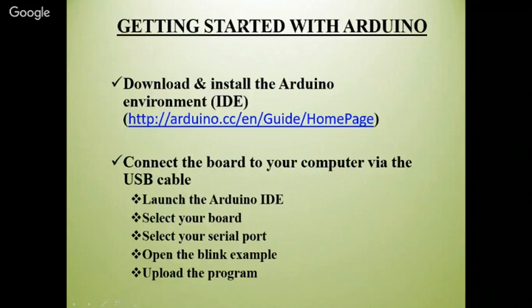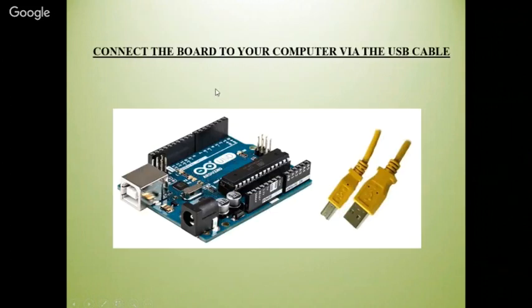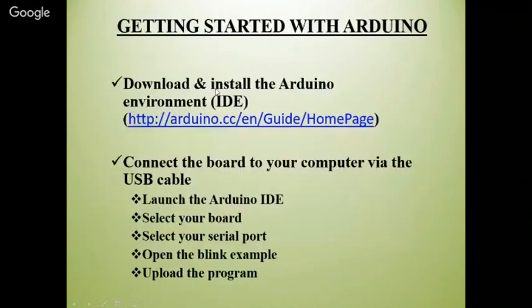To program the Arduino, at first you have to download the Arduino IDE. There's no need to install in the new versions. You only have to download and copy the setup. Then connect your board to the computer via USB cable, open the Arduino IDE, and then select your board.